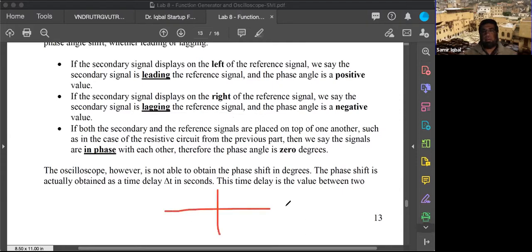If this was the x-axis and y-axis, and this is, say, the input signal, and then you measure the output, and your output is coming up like this. So your output is now a few degrees different than the input. This is the phase angle shift. I'm just picking the peak. I could have picked the minimum values also from both of those waveforms. Do you see what I'm saying? What I'm showing here is the input signal and output signal.